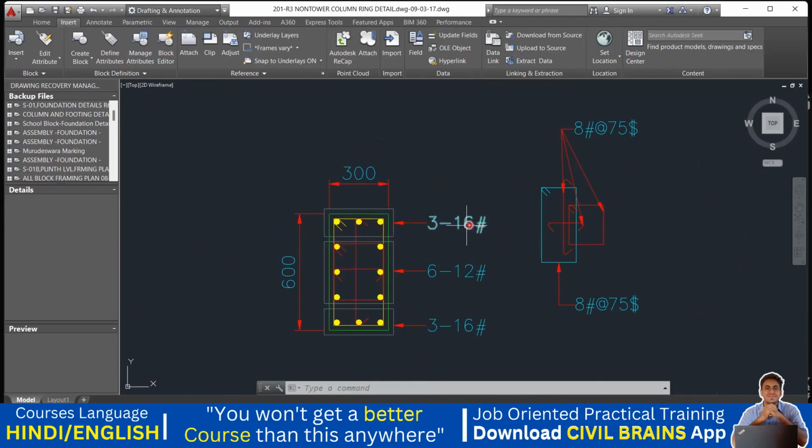So to provide 16 diameter 3 bars here, 16 diameter 3 bars here, and 12 diameter 6 bars: 1, 2, 3, 4, 5, 6. And these are your lateral ties that you are supposed to provide. Master ring, then this ring and a link. So this link will be here, right?